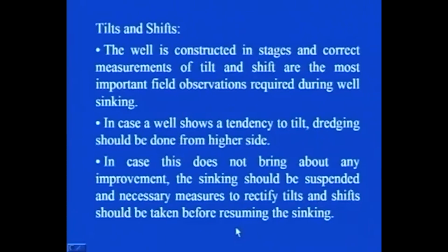So at any stage, when you see during the sinking process that the tilts and shifts are becoming more, you should stop sinking right at that stage, first try to rectify that tilt and shift, and only then go for further sinking of the well. Different methods are available to rectify tilts and shifts.